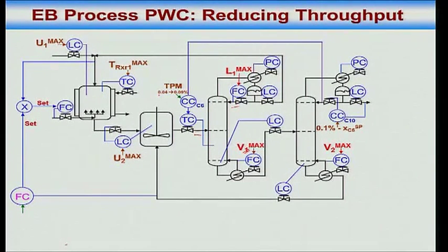Yes or no? In fact, instead of doing the ratio, I will take up temperature control whenever I can, and I will take up ratio control whenever I can. I could have also controlled the temperature by adjusting the reflux in the rectifying section. I could have done that too. It's just that this is simpler. Yeah, this is much simpler.